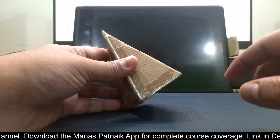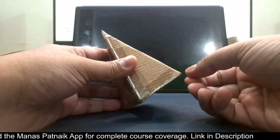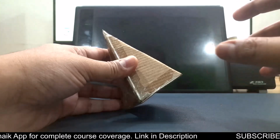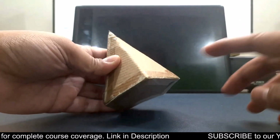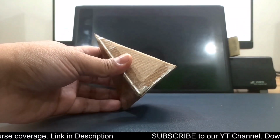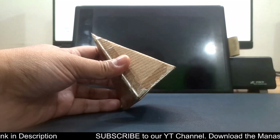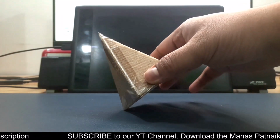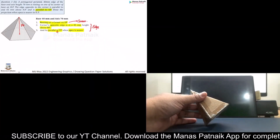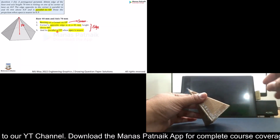Now, you are watching this from the front. So there is an edge over here, which would look like a point, but there is actually an edge. Let me turn it slightly so that you can see it. This is an edge, but when you look at it from the front, it looks like a point. This is going to be your step number 2. In the third step, again, a condition has been imposed, and that says that it is parallel to VP. This is parallel to VP.